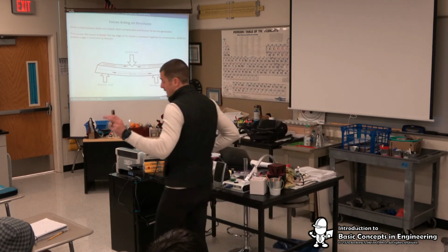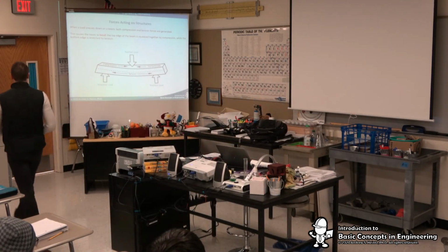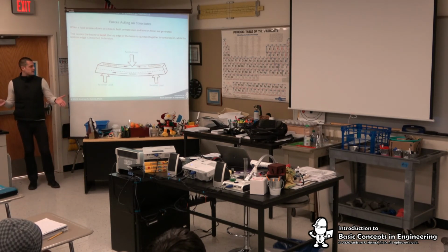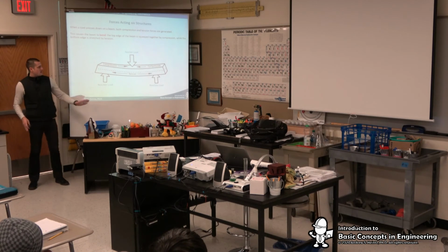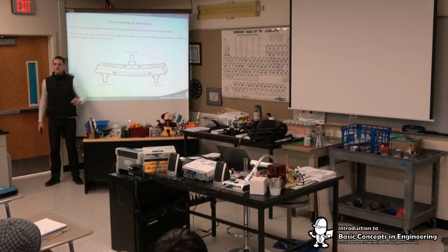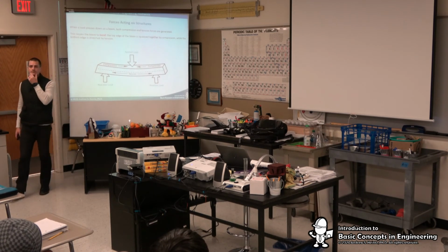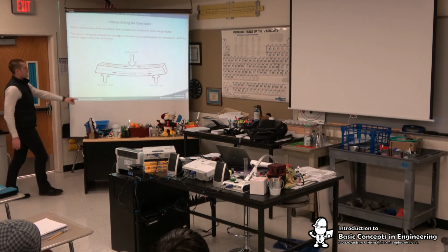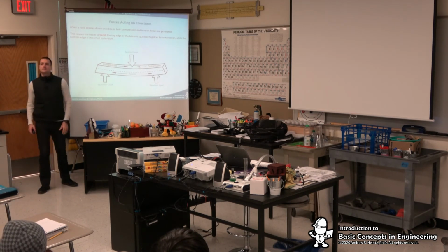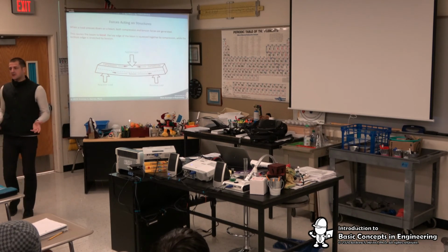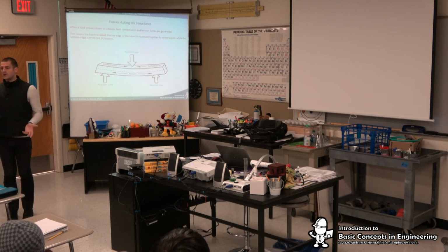So now let me ask you question number 2. If my material, so we agree it's going to fail in the middle, right? That one's pretty self-explanatory, and I agree, and well done. Is it going to fail on this side, or is it going to fail on this side of the material? What do you think? And why? It'll fail on the bottom? Yeah. You're correct. It's probably 99 times out of 100, materials will fail more under tension than they will under compression, right?